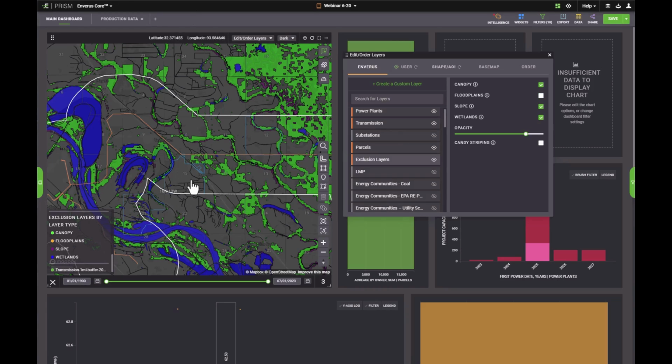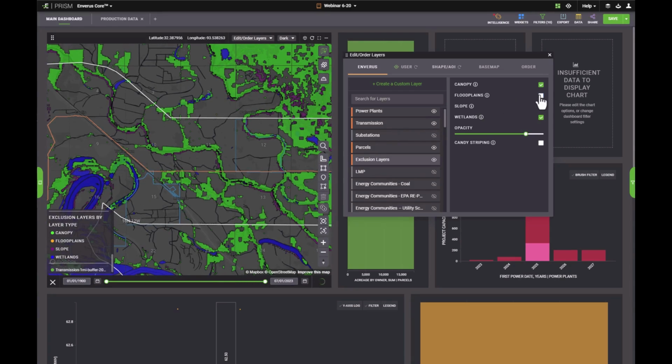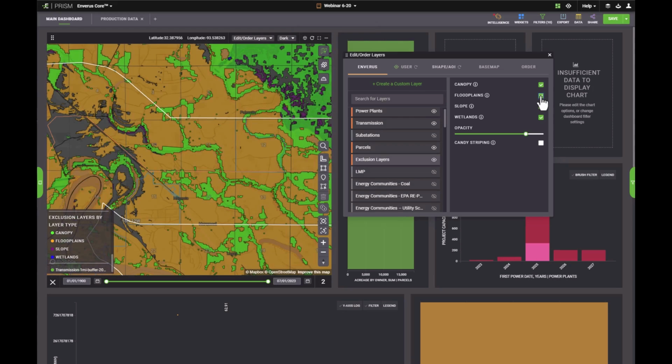And 2 of them seem to look better off. So we have the parcel in plot 15 here and the parcel in plot 12. So considering our tolerance for building in floodplains and all of the extra permitting and construction risk items, as well as operational risk items, we can determine whether we want to move forward with designing a facility on one of these particular parcels or moving and looking in another area for somewhere that's less affected by floodplains.